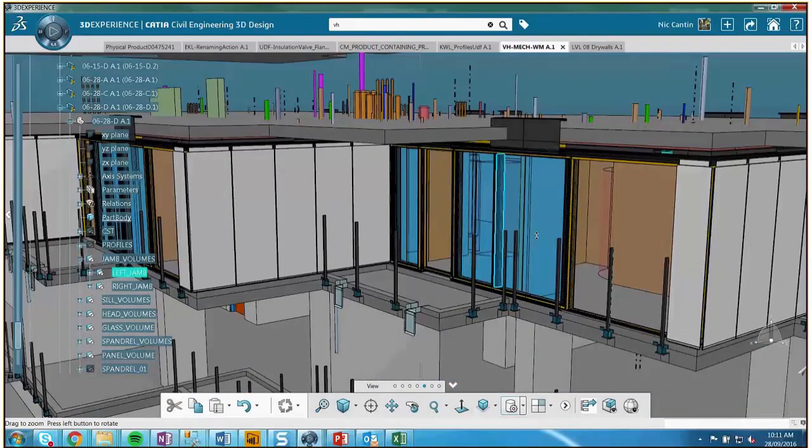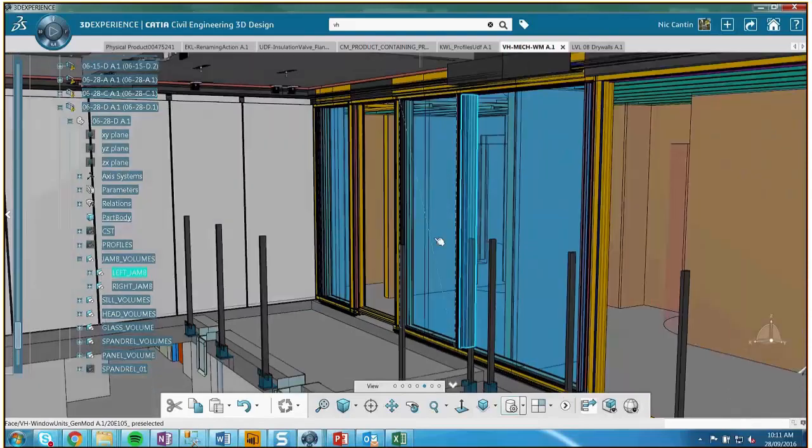And another thing you have to think about is we generated all the window types using a component family. With a component family, I don't think you can do anything at an assembly level. It's just much easier to manage everything with the component family as opposed to building product templates for everything to be managed at that level. So our suggestion is keep it feature based unless you really need every single element to be its own component. Even at fabrication, that might not be necessary. Mm-hmm.